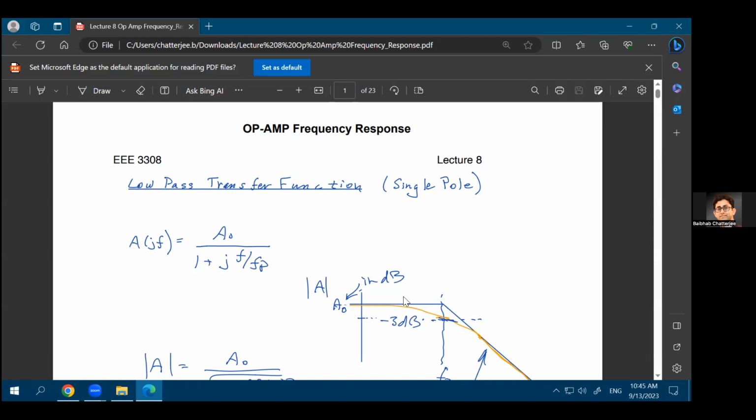So now you can write down what would be the voltage division. What would be the voltage division between this capacitor and that resistor? That voltage division between the capacitor and resistor would be 1 upon SC in the numerator divided by 1 upon SC, or let's call it SC naught, because we are calling this capacitance as C naught.